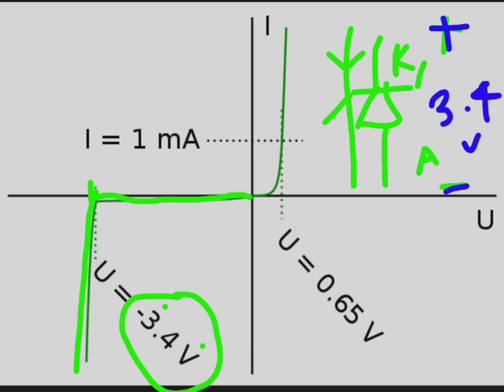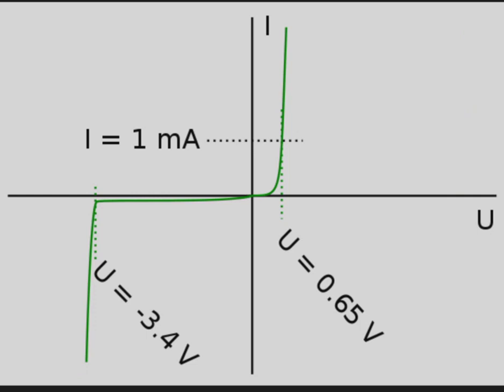So I hope you understood the difference between the IV curves. The IV curves of both the Zener and the normal diode look the same, but the main point here is the concept of breakdown voltage, and after the breakdown, the Zener maintains a constant voltage drop across its terminals. However, that is not the case with a normal diode.